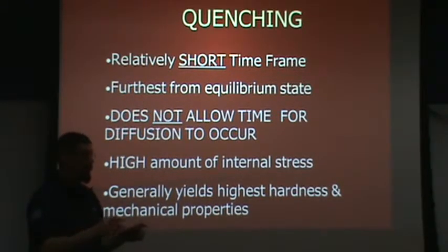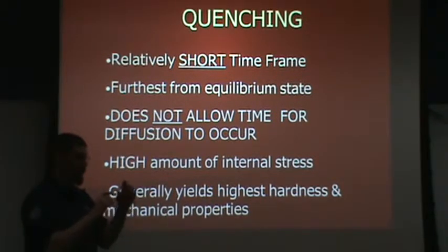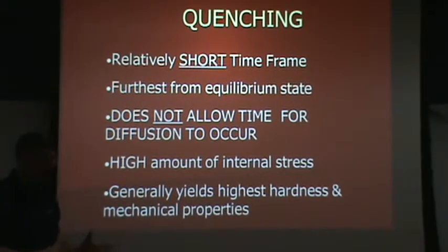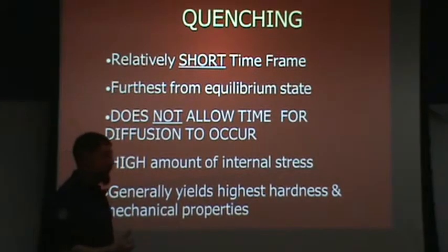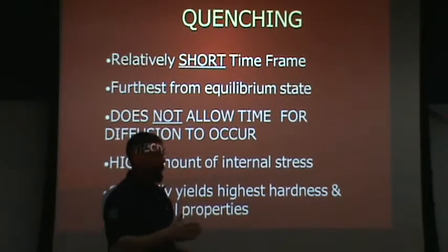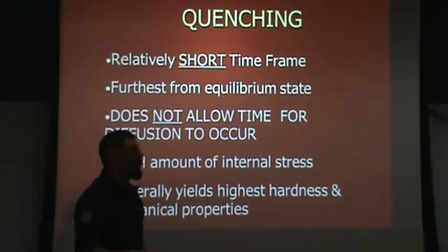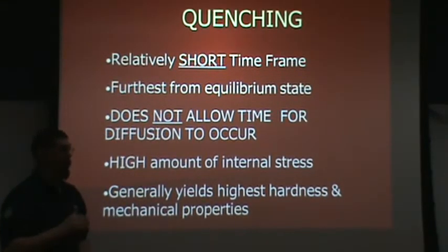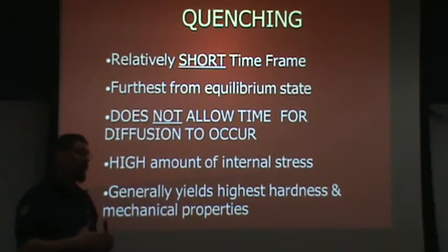The hold time is not going to affect the grain size because the grain refiners are what control the grain size. The temperature and the distribution of grain refiners are what control the grain size. But I do get some changes by extending hold time, in that with a short hold time, I may not fully dissolve other constituents, other kinds of carbides, so iron carbide or chromium carbide or something like that.